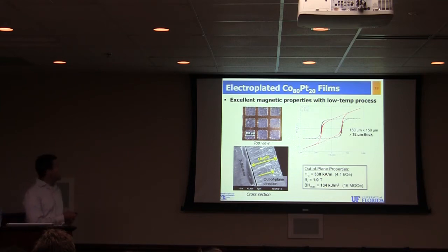And the nice thing about these magnets is they give their strong magnetic properties in the as-deposited state. You deposit them, and they're ready to go. You do a pulse magnetization process. You have to apply a single strong magnetic field to magnetize the magnets. But at that point, with no further work, they're ready to use.